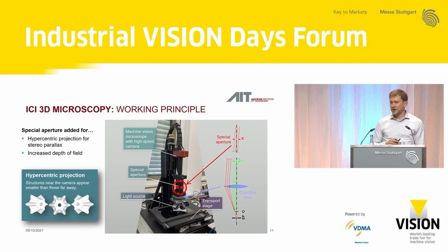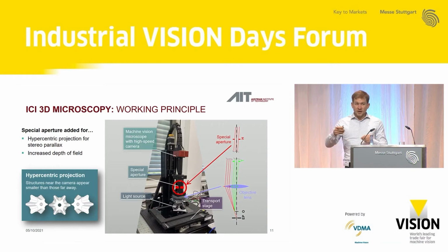Beneath the microscope, we can see an illumination source. It's also custom built. We have 6 illumination directions. This helps us a lot to suppress gloss artifacts, for example if you do inspection of metallic surfaces, because we can measure the photometric response from 6 different illumination directions, and then find the images which are properly illuminated and don't show specular reflections, and with that we get very clear and speckle-free images.